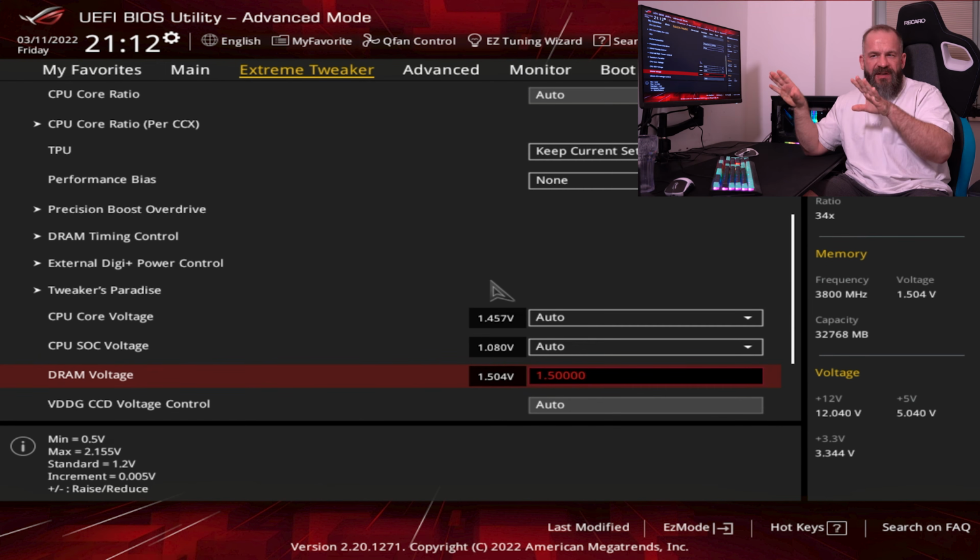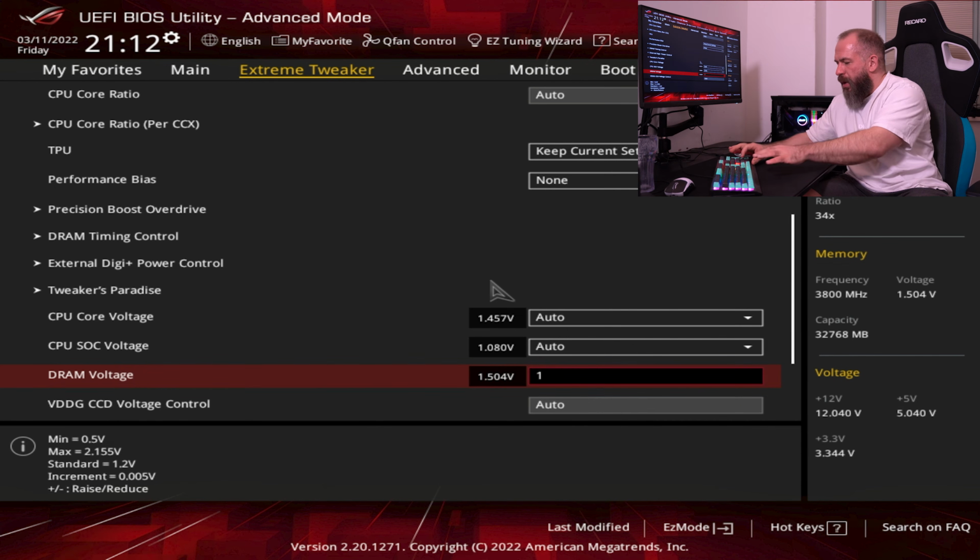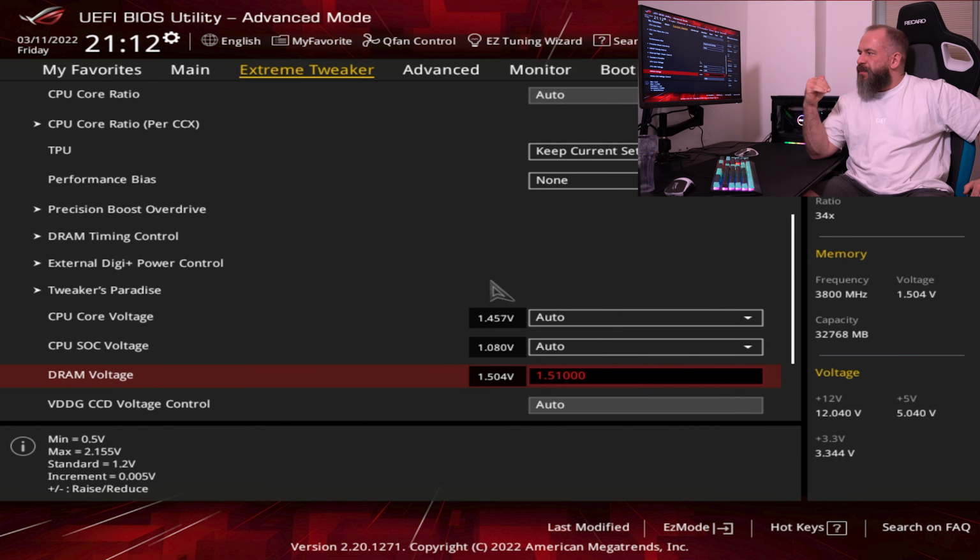But sometimes, just by how the board is made, it goes down to 1.49 and 1.48. And at this point, the latency and the way the DOCP is working for this one is totally trash, and you really feel that the flow is just destroyed directly. That's why I always go for 1.51 volt. And this always keeps me above 1.50. Always. I never go down. That's most important. And with these settings, I have very good latencies and workloads, and everything is super with this one. You can just test it for yours.